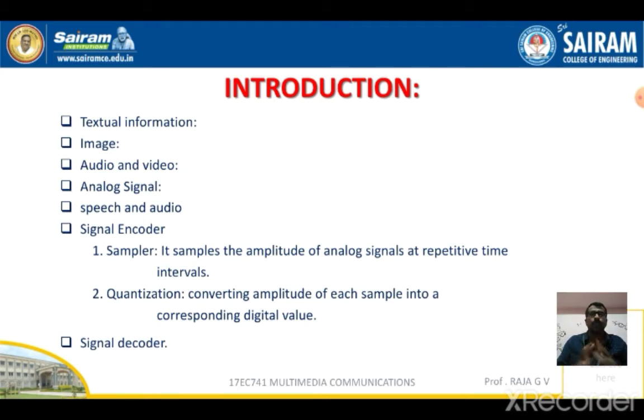In order to store and process the signal as a type of media within the computer, it is necessary to first convert any time varying signal into digital form. In addition, the signals used to operate devices such as loudspeakers for speech or audio signals, and computer monitors for display of digitized images, are also called analog signals.